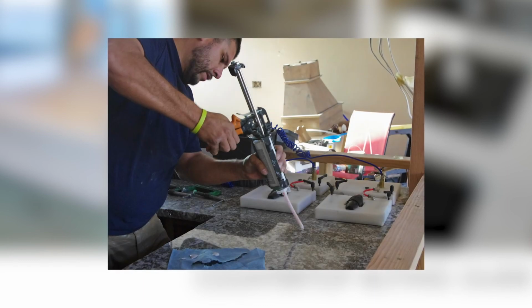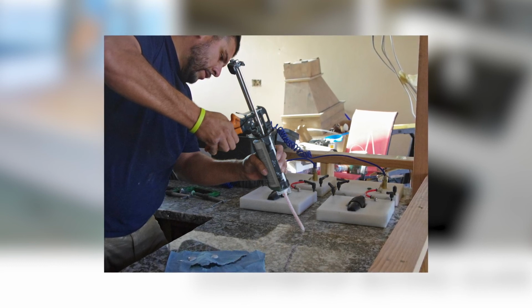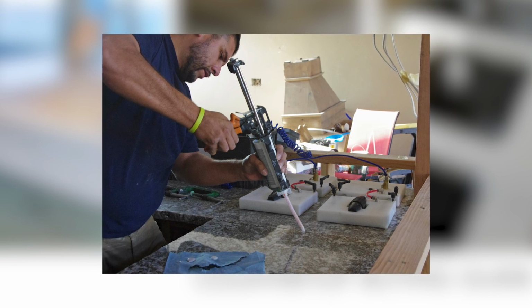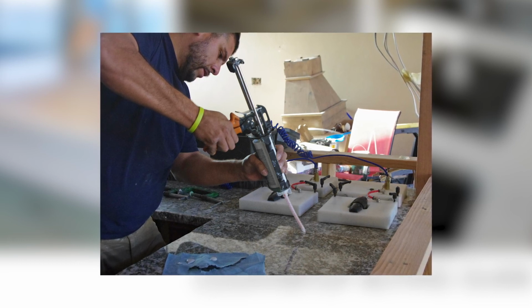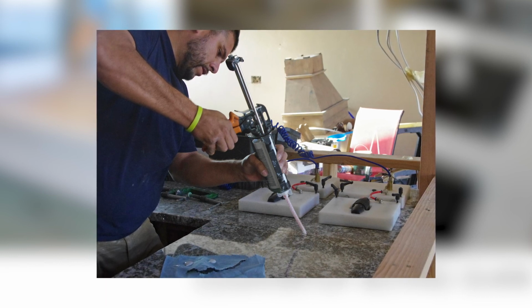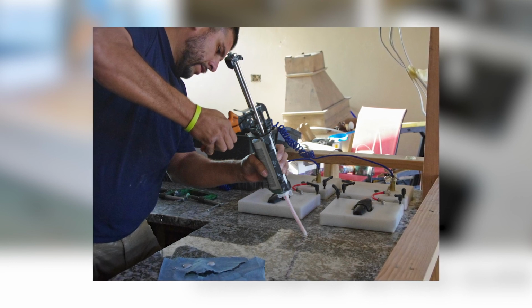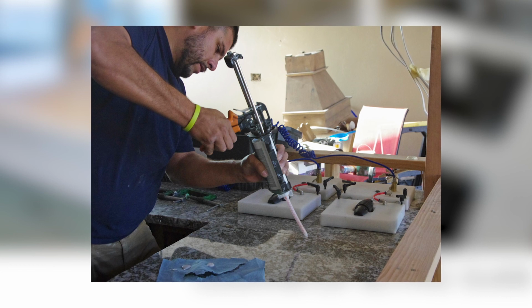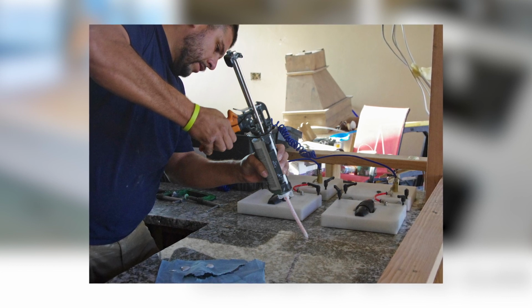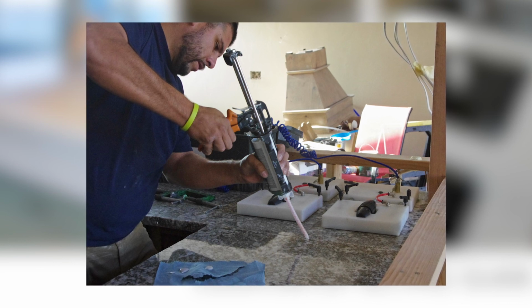Caulking. Undermount sinks, backsplash, and counters are caulked during installation. Depending on the stone, a white or milky white translucent caulking will be used. Typically, paintable caulk is used where stone meets sheetrock, and 100% non-paintable silicone caulking is used where stone meets stone or stone meets cabinets. Please inform your sales consultant if you have any special color requirements for caulking. Caulking requires regular maintenance and may shrink over time. For those who participate in our annual stone care, caulking will be touched up as needed.